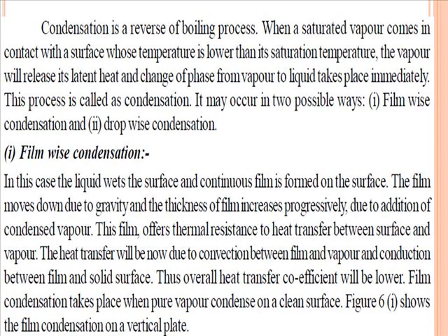When a saturated vapor comes in contact with a surface whose temperature is lower than the saturation temperature of that substance at a given pressure, the vapor will release the latent heat, very important, latent heat, and change phase from vapor to liquid immediately. This process is known as condensation.